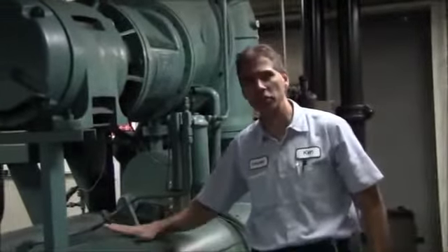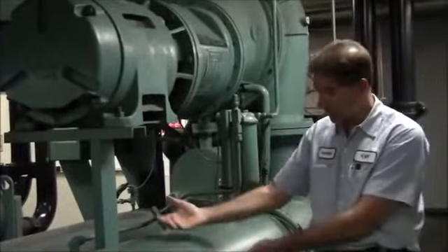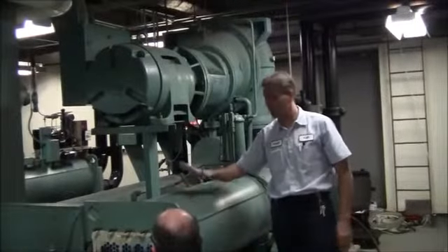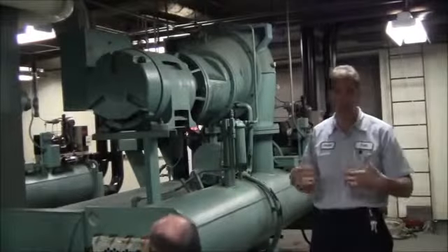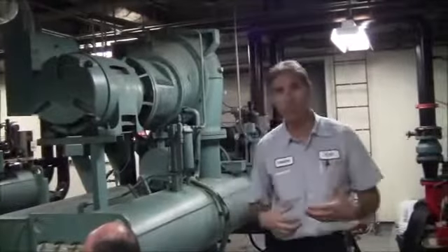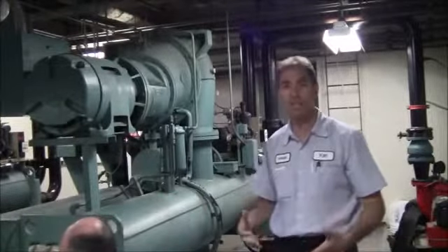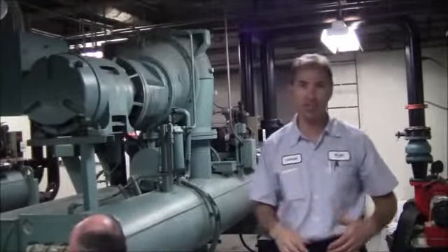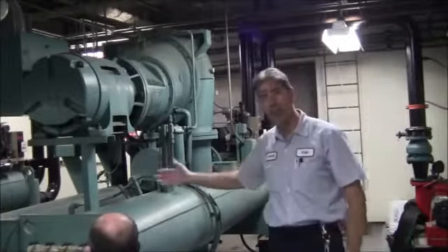So these are shell and tube heat exchangers. You've got tubes and it's just surrounded by a shell. Inside the tubes in this one here is condensing water. You can build up some type of calcium, magnesium deposits and things of this nature on the tubes. You want to keep your tubes clean, so you have water treatment that goes on to make sure you've got the right chemicals in there. And then due to the age, we're concerned about how long these tubes are going to last.